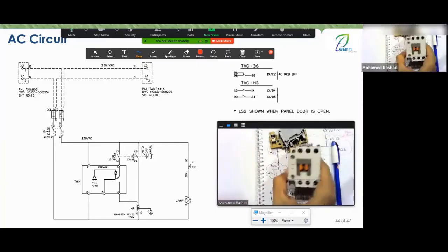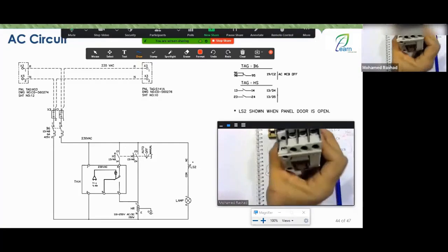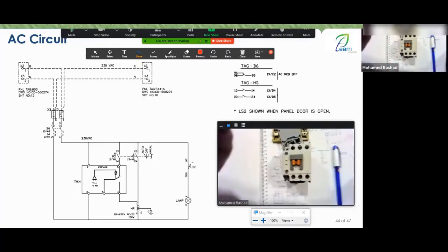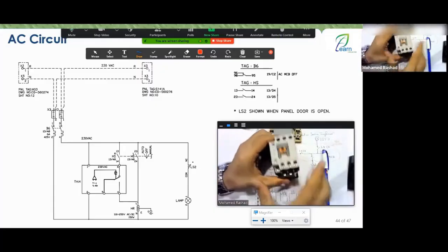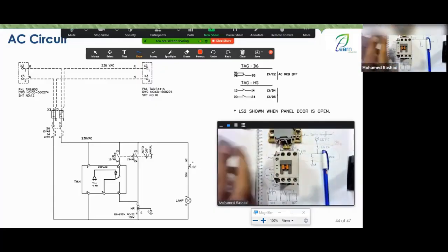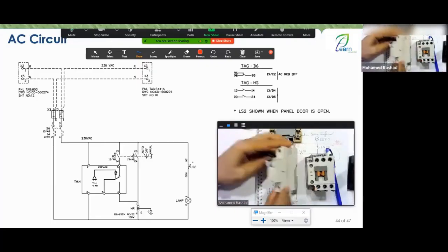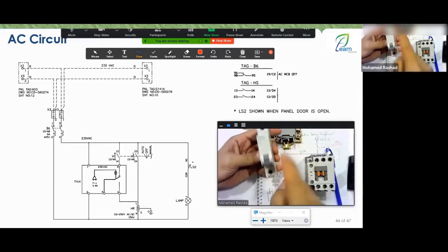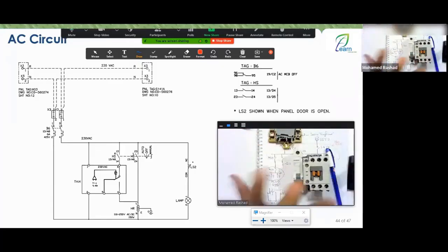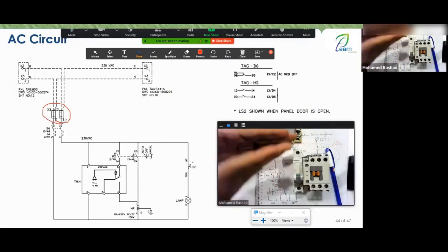So instead of having moments where you bring a connector like this and you are the only one with this connector installed in your cell, and for example, it's full of wires and you want to connect to the terminal here or want to connect to the terminal here, or like the miniature circuit breaker, the small electrical switch like the one you have in your apartment, for example. All right, you want to connect the terminals here, so the matter is correct. You will always find that the termination must be on a terminal block, to make measurement operations easier for you and also to facilitate troubleshooting. Or, the idea that you have divided the circuit into more parts.